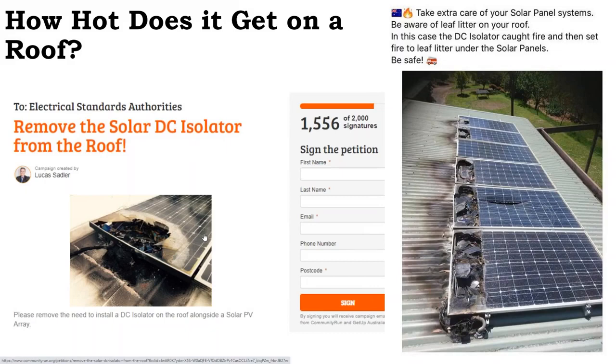What I would say is if there's trees nearby, to the point where it's not just that there's branches nearby, but that you could get leaves falling onto the roof under certain conditions. If you get leaves on the roof, you want to have a net around your array so that those leaves do not get underneath the array where they can get caught up on the racking and the wiring.